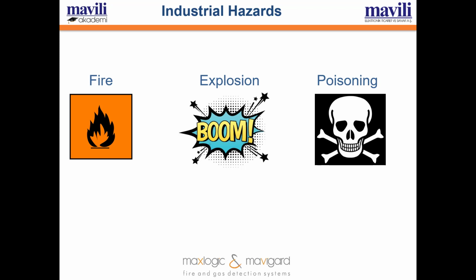First of all, explosive and toxic chemicals in industrial facilities should be analyzed. With this analysis, which chemical is present at which point of the facility? Which chemicals contain explosive or toxic gases? It's necessary to make a design to prevent dangerous chemicals or possible fire risks at the points mentioned in this report. Along with the hazard analysis report, a site classification of the facility must also be made.